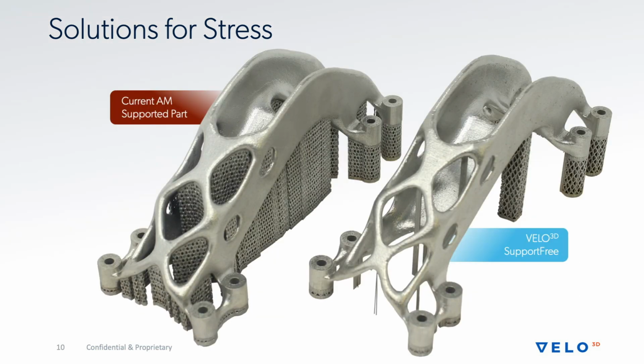So what Velo3D has done is created a much more comprehensive process parameter set. What I mean is that when you run through our print preparation software, the software automatically applies a very large set of many processes. You may have as many as 24 individual different processes being applied to a single part. They're automatically applied, and each of those different processes create a somewhat continuous blend of process to ensure that